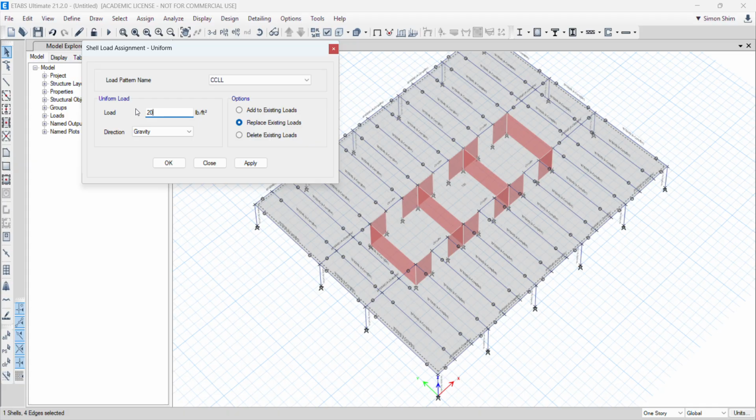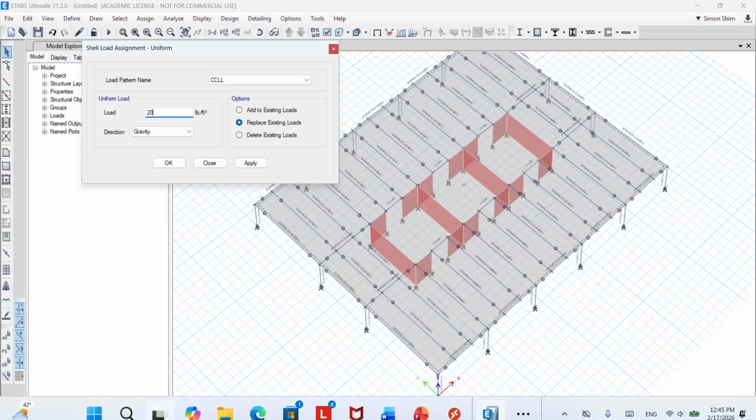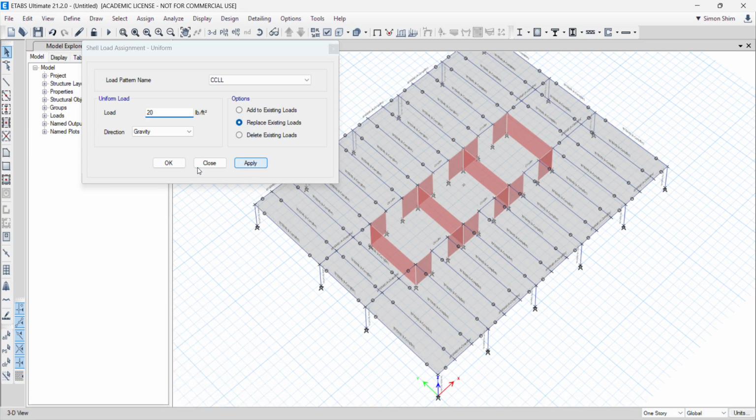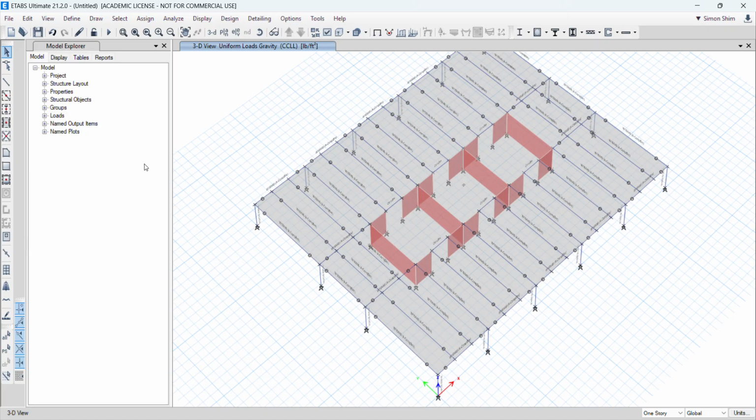But after the concrete is fully cured, the beam and concrete are really stitched together, right? In that permanent condition, we are also checking for permanent loading. I will explain that after that. So I'm gonna assign 20 psf construction live load, right? So assign it. So when you do that, it's ready to run.